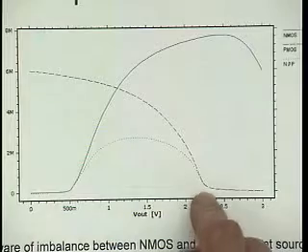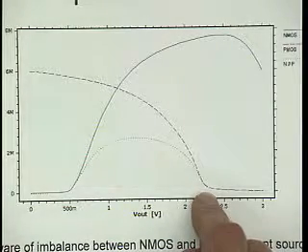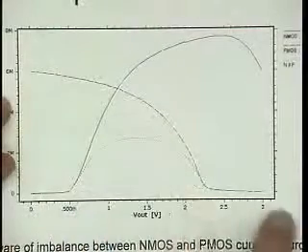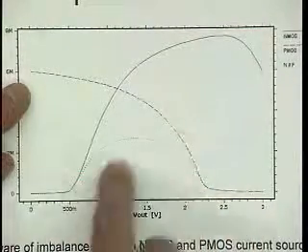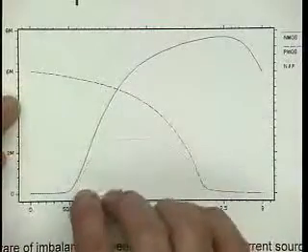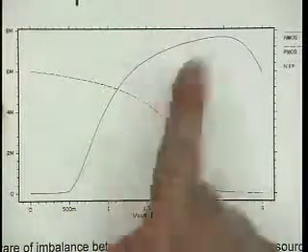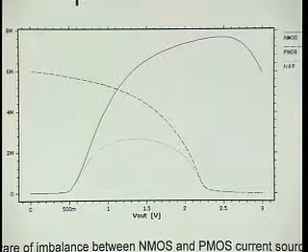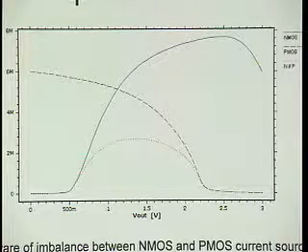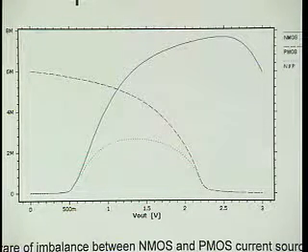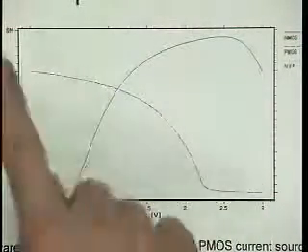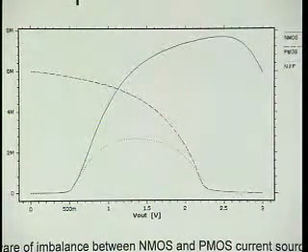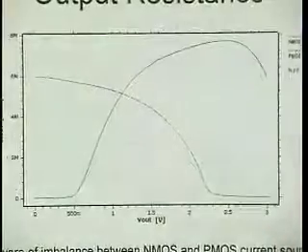In that case, of course, I would have to improve the NMOS only, and so here I get the output impedance just of the PMOS branch and the NMOS branch, and here I can see that they're actually not so poorly matched, but the NMOS has a little bit higher output impedance. And so you will frequently see published amplifiers where one of the current sources uses boosters, but the other one doesn't. That designer went through this exercise, plotted this, and said, well, gee, I don't need the gain booster for that one, I need it for the other one. Okay?